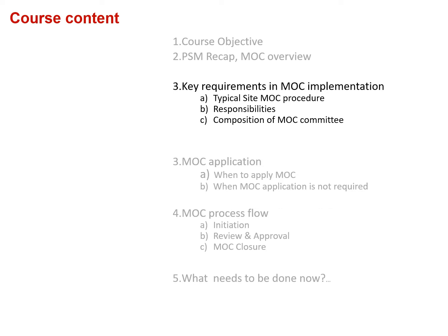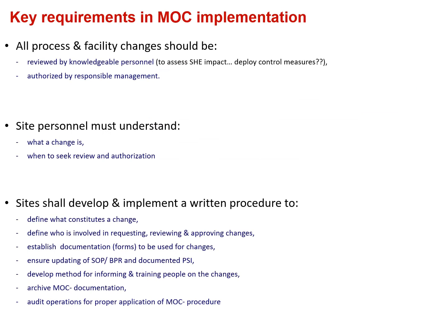What are the key requirements in MOC implementation? All process and facility changes should be reviewed by knowledgeable persons, so-called subject matter experts, SMEs, and authorized by responsible management. Site personnel must understand what a change is. The persons on the shop floor or the cross-functional team should understand what change is happening on the shop floor, whether it is a pipe change, process change or equipment change, and when to seek a review and authorization.